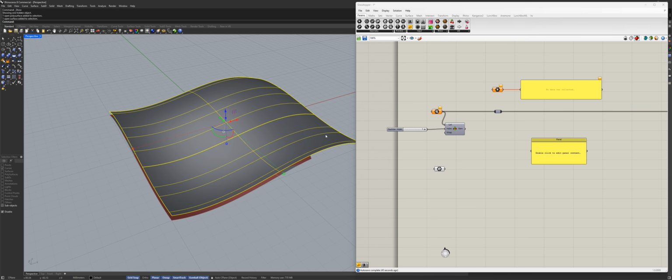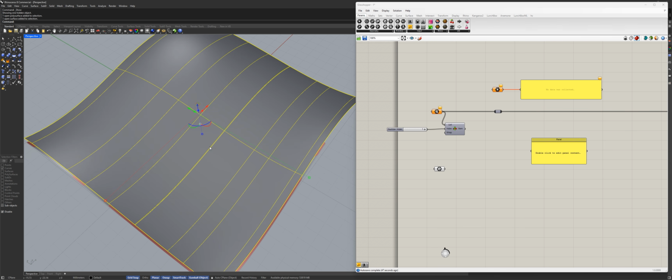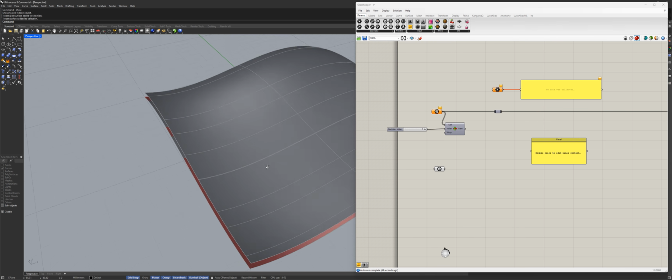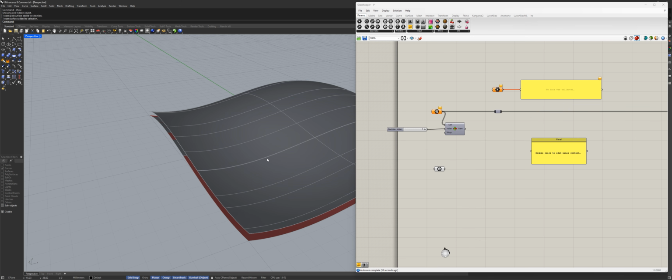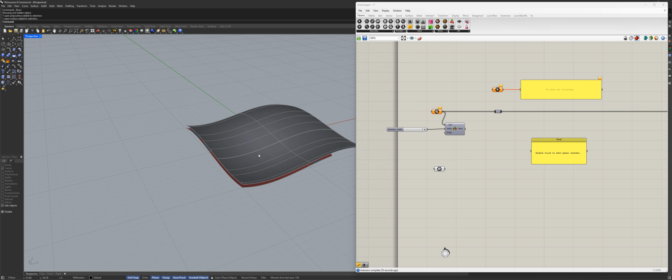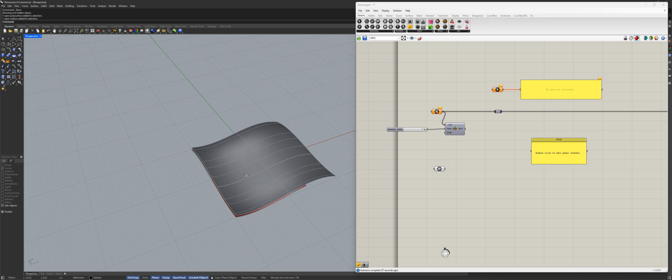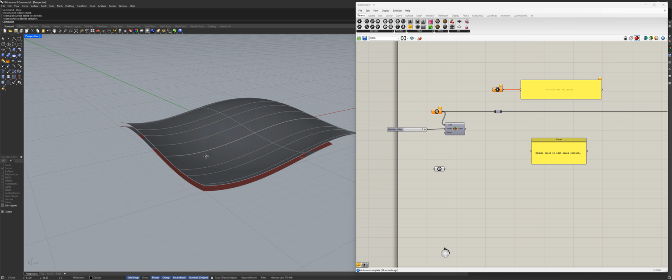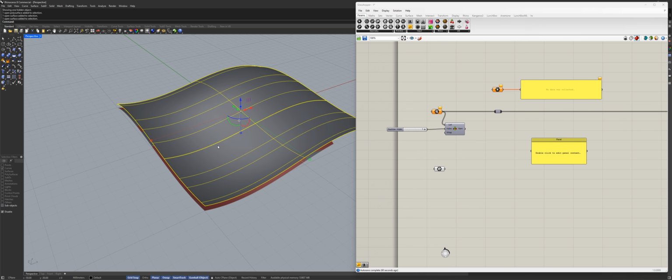So let's see what's inside and let's look at the surface. Now, first things first, this surface has a lot of spans. This is horrible for surface modeling, but it's absolutely okay for parametric design, because in our case, it's supposed to represent, not to be accurate in itself. So let's first check the direction of the surface, because different systems orient surfaces differently.